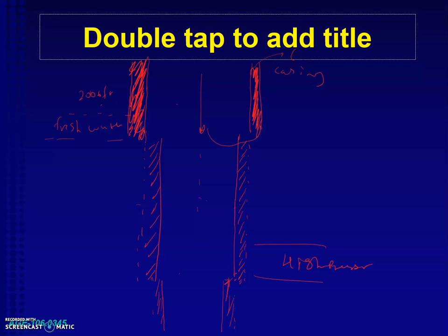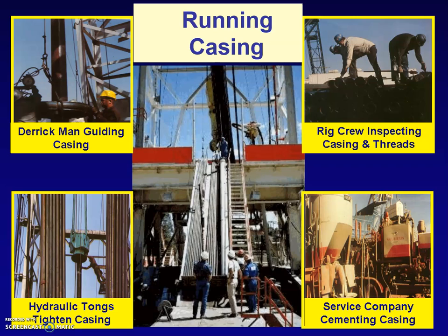Now, if your oil and gas are coming out of the wellbore, then there is no connection between your hydrocarbons and other formations that they are passing through. So this is the benefit of having a casing, and all the wellbores currently drilled have casings, and that's what I wanted to talk about here.